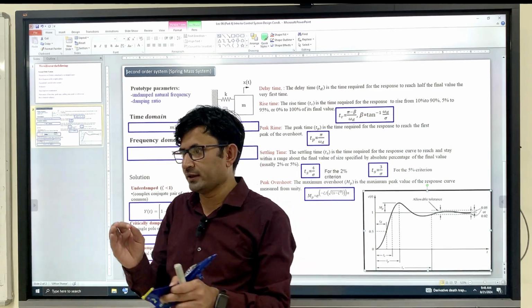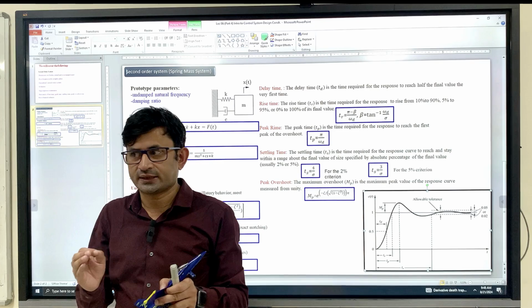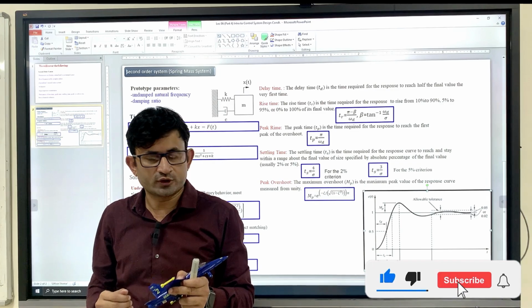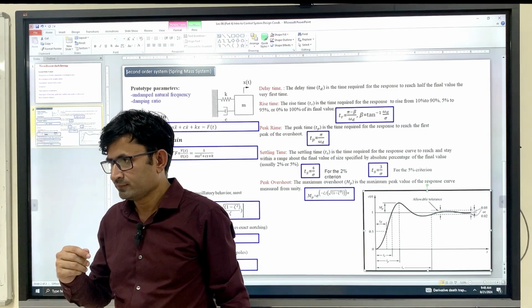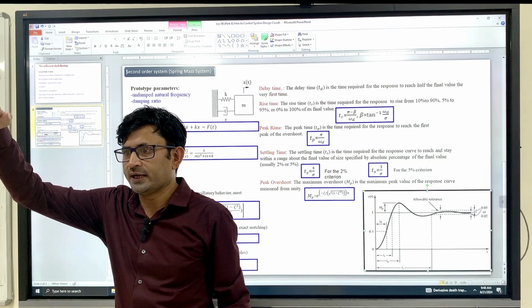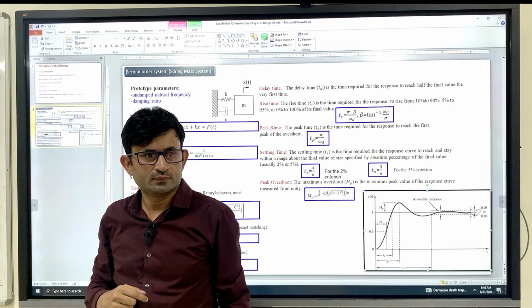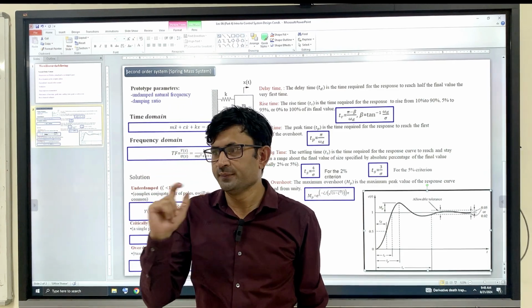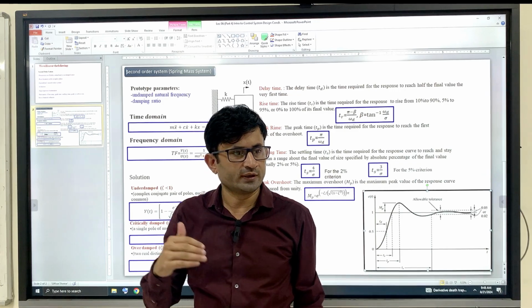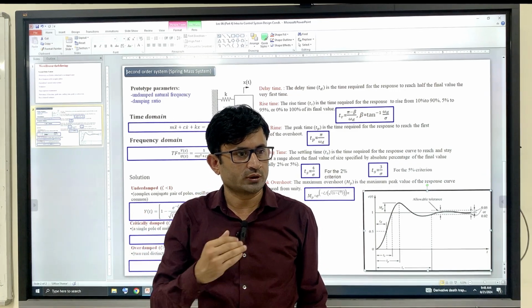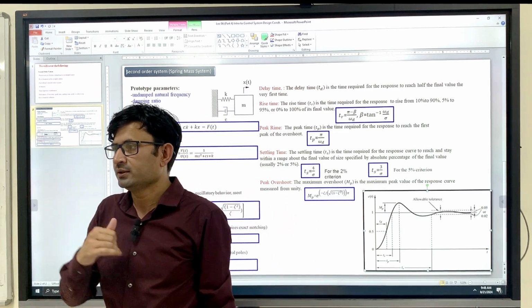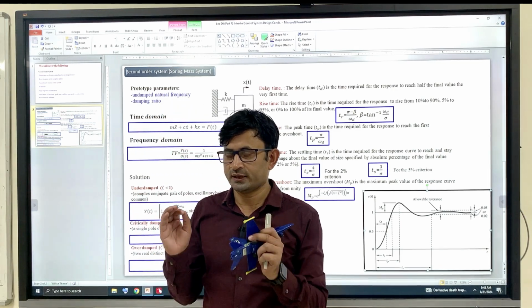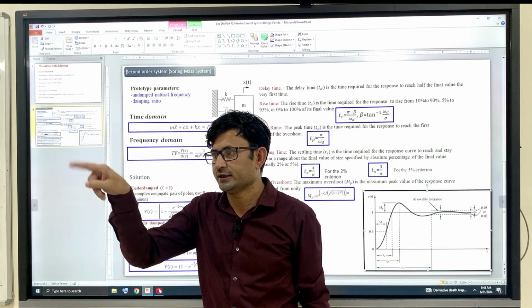So that is why it is very dangerous at the time when the actuator saturates. For example, you commanded the thrust to hover the vehicle, and the motor got saturated. In this condition, if you are not limiting the value of the integral gain, it will keep providing control input, control input, control input, and you will not be able to recover the system back to the normal flight condition. So you have to be very careful with the integral, because it's an integral of e dt, right?